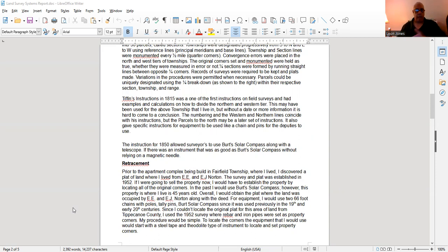And then they called them tally pins. We used to call them taping arrows. So I would put an arrow every time I ended in 100 feet, and turn angles, because it's very important that you do this right, because you want to mimic the original survey. That's the whole point. The system was set up so we can retrace everything. And it's a good system.